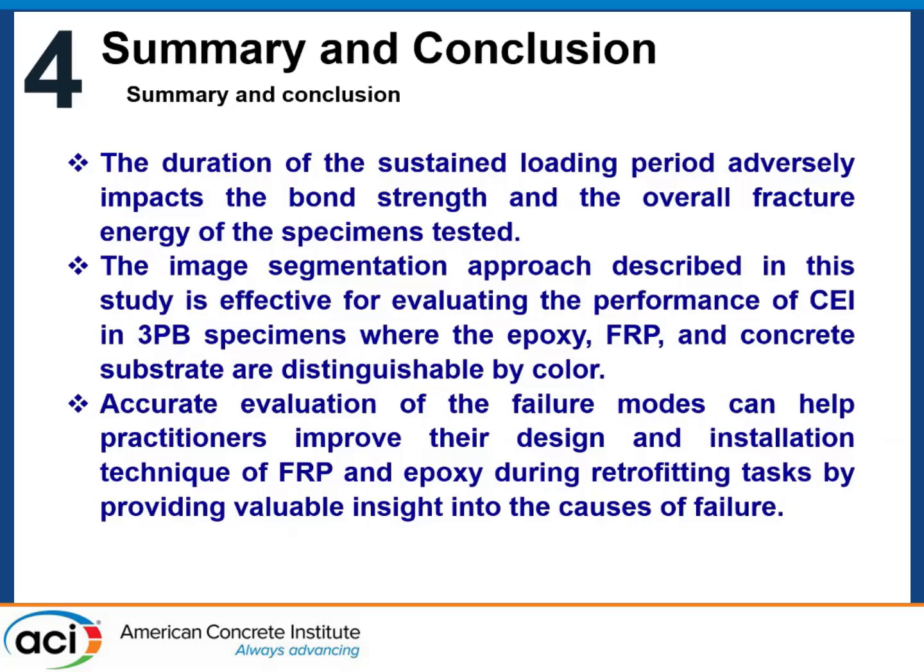So as you put blue on black, the difference in the hues that you're trying to capture is going to be less significant than when you do blue on concrete, which is going to be in the whitish, grayish range of the spectrum. So, lesson to be learned: if you want to capture what happens between the FRP and the epoxy, you need to make sure that those two colors are as different as possible to start with.